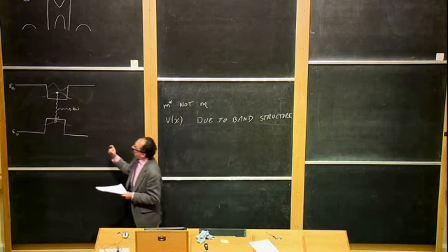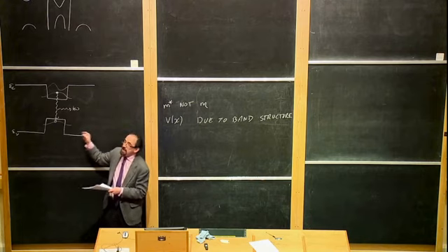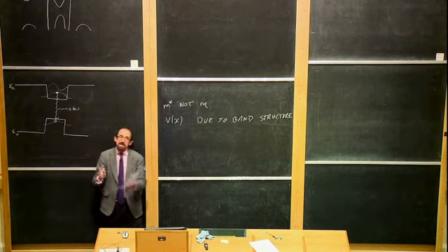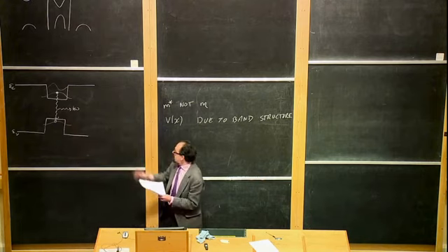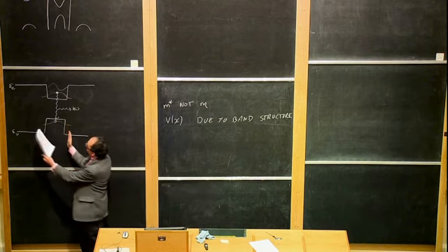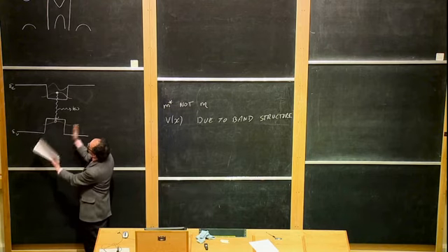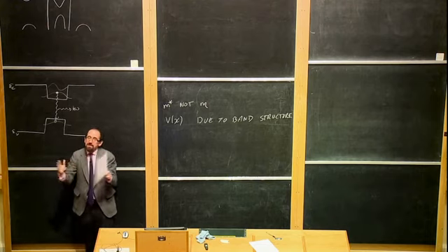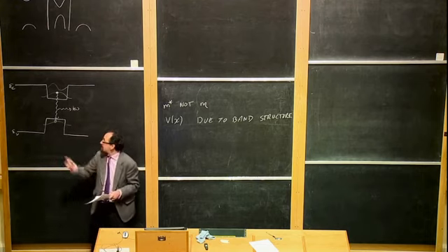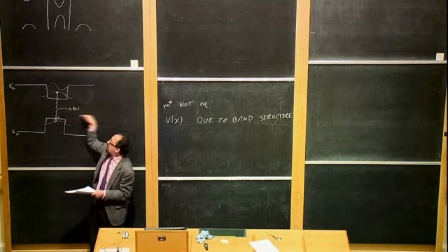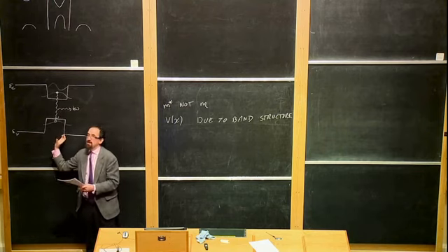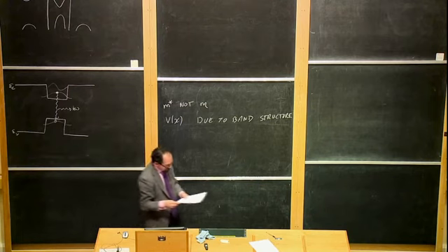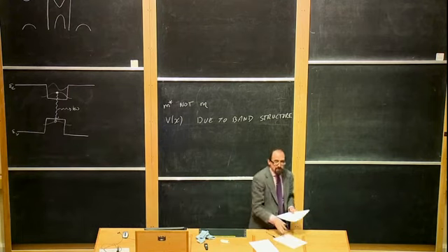The thing that's neat about this structure is you can change the energy of the eigenstates by changing the width of the well. So if you make it a thinner layer of gallium arsenide inside aluminum arsenide, then the energy eigenstates change, just because the energy eigenstates always depend on the width of the box. And so you can tune the energy of the outcoming photon by just changing the width of the well. And that's why this kind of device is frequently used in optoelectronics.